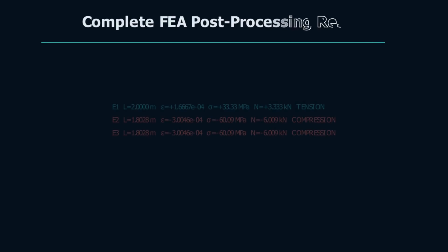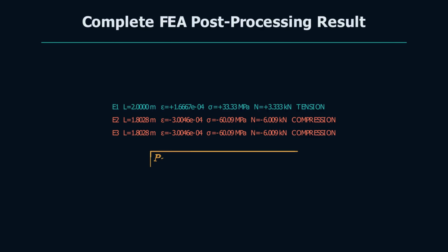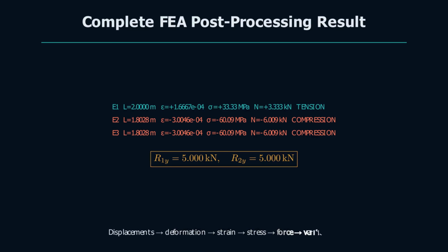We can now summarize the complete structural response. The bottom member is in tension, the two inclined members are in compression, and the support reactions are 5 kilonewtons each.